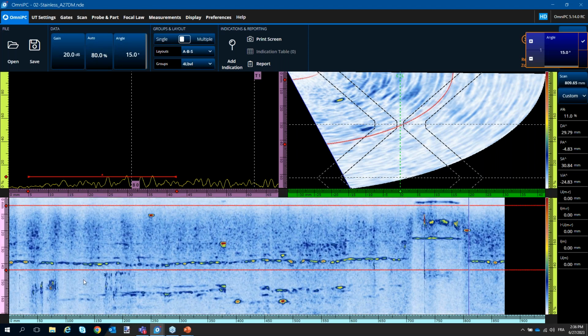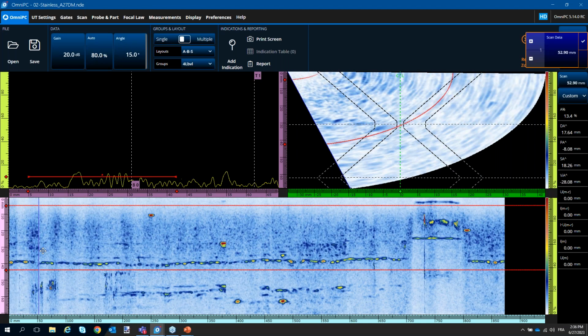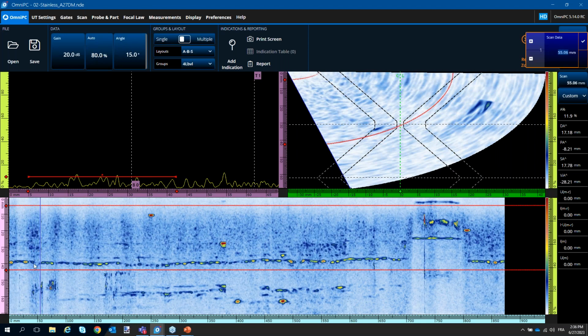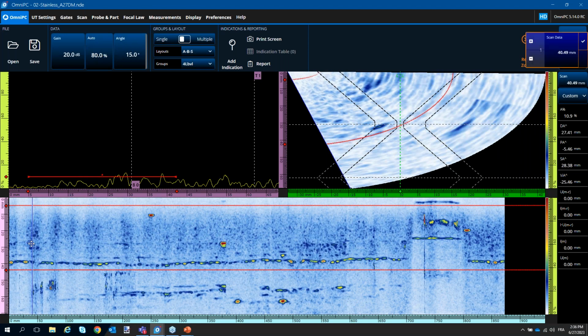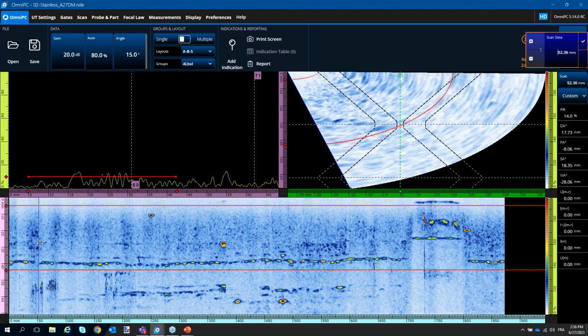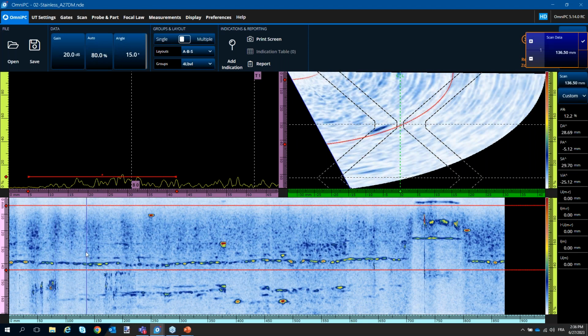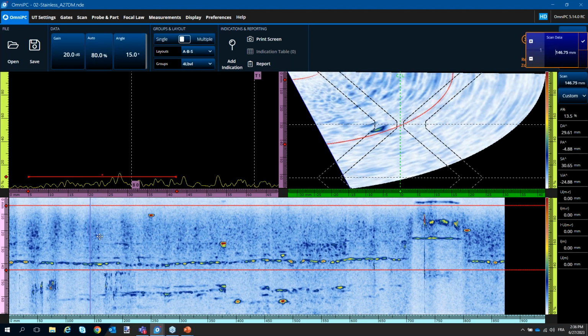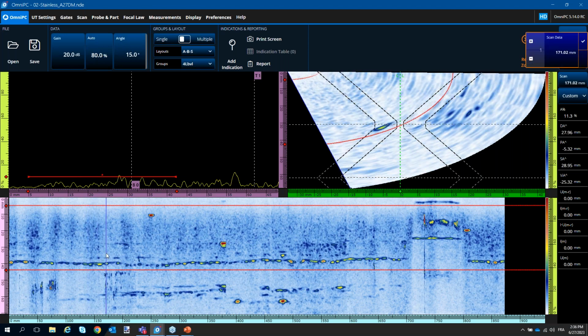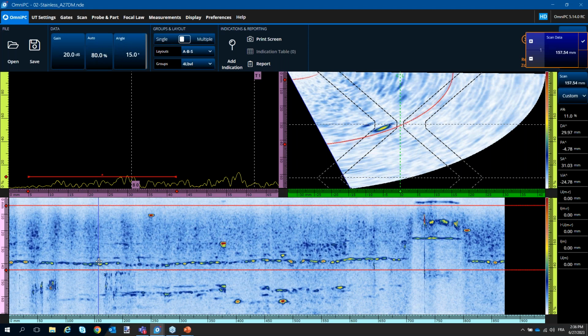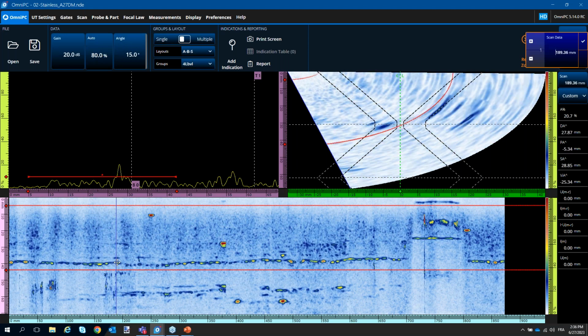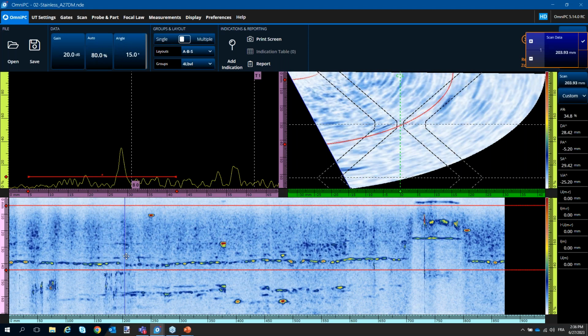If I activate the merge B, now I can see a lot of things going on in the same display. So all I have to do is review each suspect indication, like I could have here, but I quickly realized they're more or less relevant. And as I'm moving on, I'm particularly interested in the area at the top of my merge B and anything above the root here, root geometry, just in case it could be an ID crack showing up.